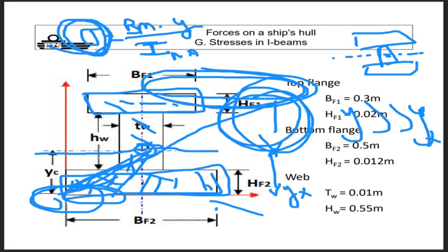A bit more downwards, a bit more upwards, perhaps perfectly in the middle, then you know compression and tension are nicely distributed. But when it's a bit more downwards, like most of the time it will be because I will make exercises similar to vessels as you have in reality, then you will see that your maximum stress level will be higher at your upper deck and lesser in your double bottom. And those are links connecting ship construction 1 to ship construction 2.